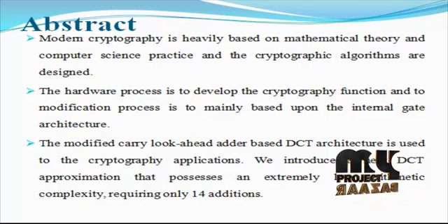Video processing systems such as HEVC requiring low energy consumption, needed by the multimedia market, have led to extensive development of fast algorithms for the efficient approximation of 2D DCT transforms. The DCT is employed in multimedia compression standards due to its remarkable energy compaction properties. Multiplier-free approximate DCT transforms have been proposed that offer superior compression performance at very low circuit complexity.